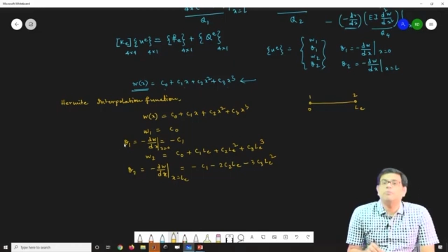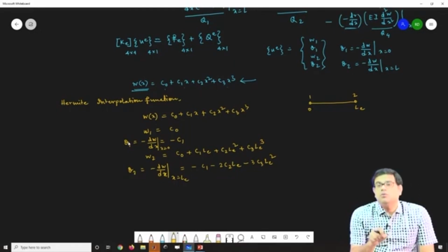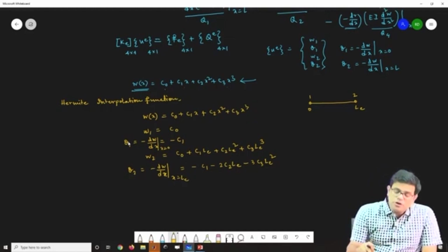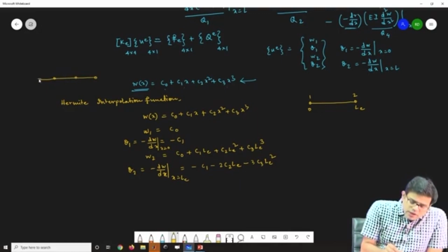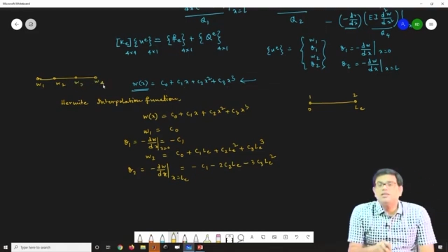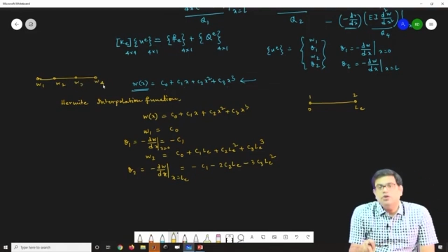There we had only the primary variable at the nodal points, with a 4 node element so that I have W1, W2, W3, W4, which does not assure me that the derivative will be continuous; in fact, it will not be.